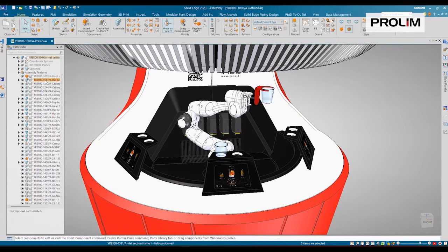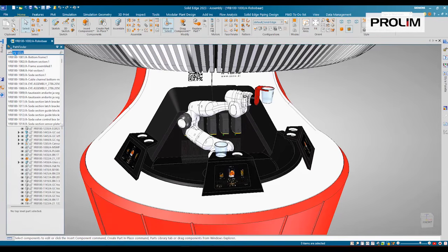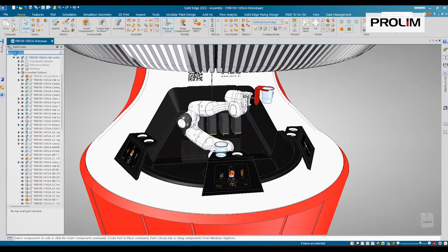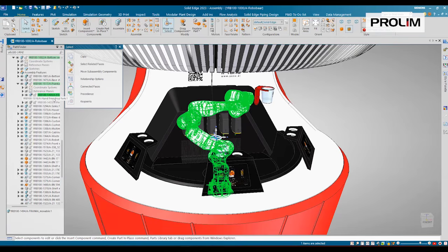Again, using the Pathfinder and utilizing the new search bar in the Pathfinder, we can search for parts that we may know where they exist inside of the design, but that's not always the case. And maybe all we have is the part number. We can either search down the tree of what could be hundreds or thousands of parts, or we could now quickly search for these elements right here in the Pathfinder. So we'll do a quick search here. It highlights it for us in the Pathfinder.